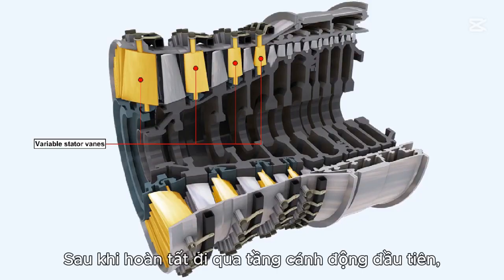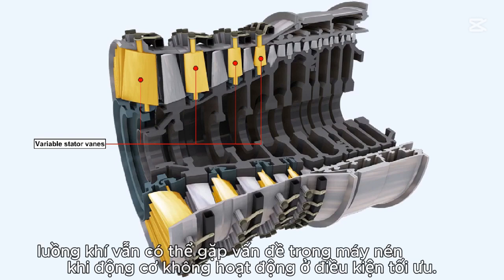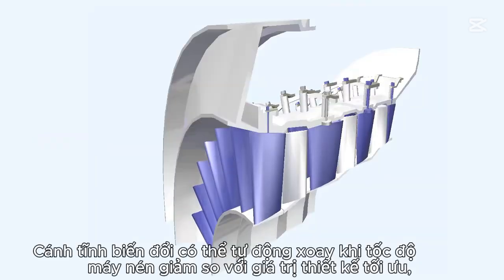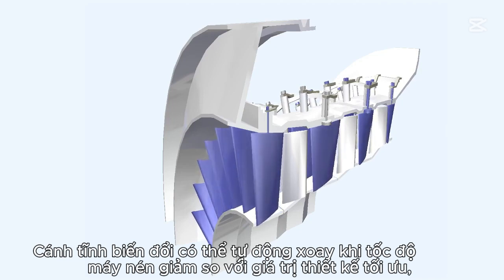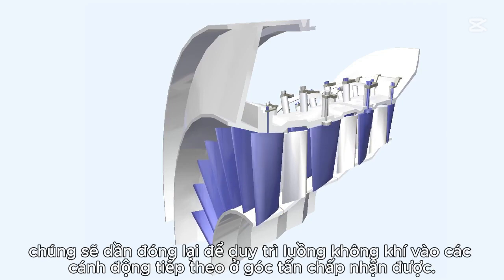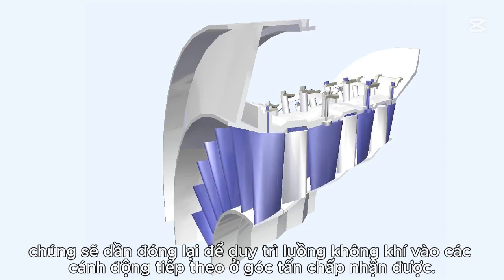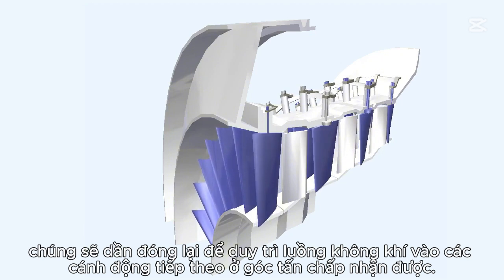After the first rotor stage has been successfully negotiated, the airflow may still have problems further down the compressor, when the engine is operating at other than its optimum conditions. To minimize those problems, some engines are fitted with variable stator vanes. Variable stator vanes can be pivoted automatically so that as the compressor speed is reduced from the optimum design value, they are progressively closed to maintain the airflow onto the following rotor blades at an acceptable angle of attack.